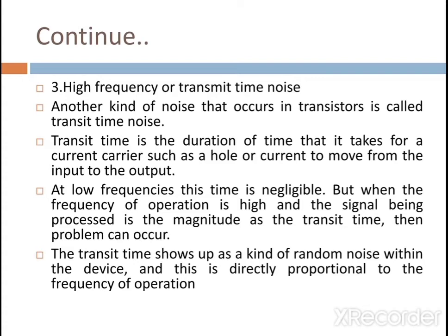Then at low frequency, this time is negligible. But when the frequency of operation is high, then the transit time becomes comparable in magnitude to the signal period, and problems can occur. Transit time shows up as a kind of random noise within a device, and this is directly proportional to the frequency of operation.